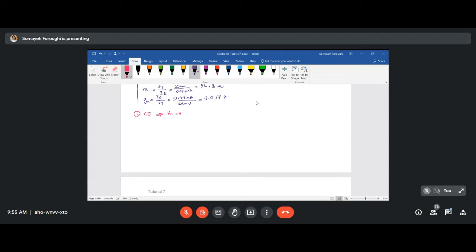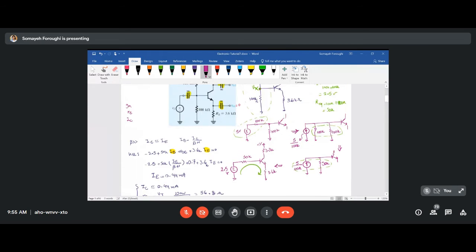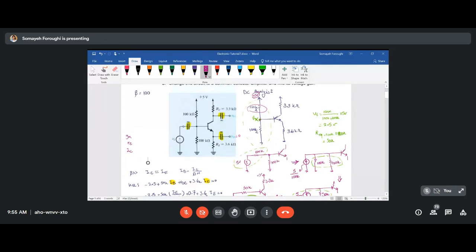Then finally, in our AC model, and remember this is our AC analysis, if you just take a look at it one more time, in our AC analysis, this first capacitor on the left will be a short circuit, then VI will come into the circuit, the O1 will go to 0, then it means from the emitter there will be just a ground, and the top capacitor will also be short circuited. It means your output will be from the collector.